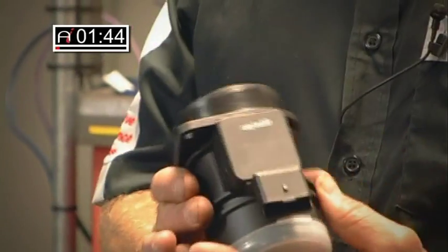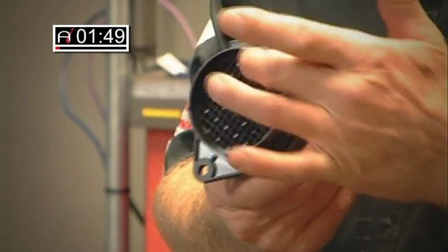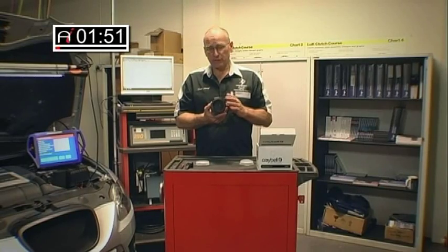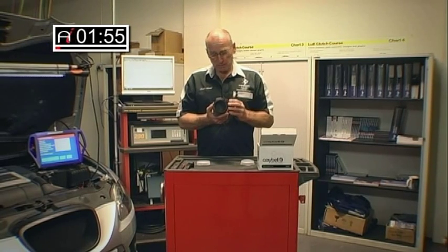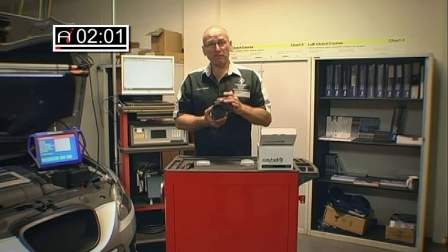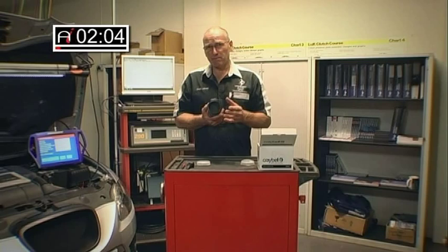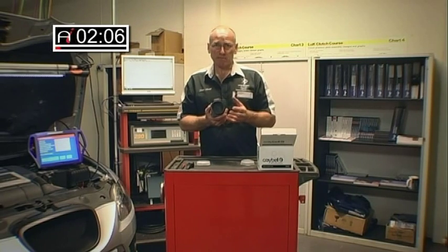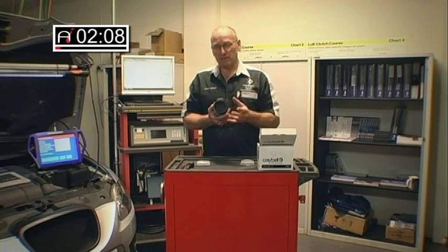Some of these sensors have what's known as a diffuser. The diffuser is quite important. If the turbulence of the air were to become, shall we say, quite volatile, then the accuracy of the air mass meter is affected. In some cases, when intake systems are modified with sports induction systems, it often does disrupt that turbulence.